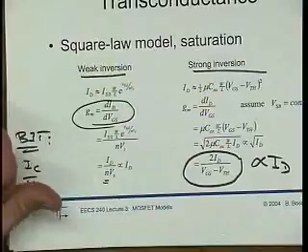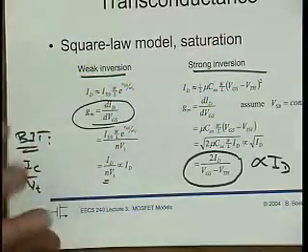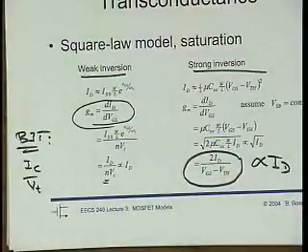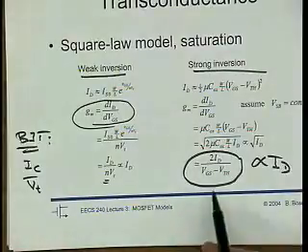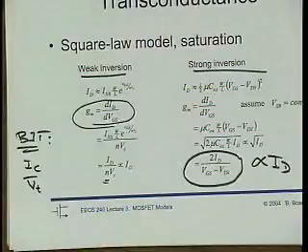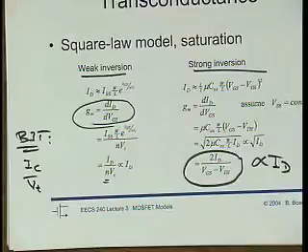Right? And that is also something that we've got to be very careful about. The opportunistic and mathematical thinking is, heck, why not? Let me make VGS minus VTH 1 millivolt. Then, well, VT is 25, right? Then I do a lot better than a bipolar transistor. So why isn't a MOS better than a bipolar? Did we just invent something great?